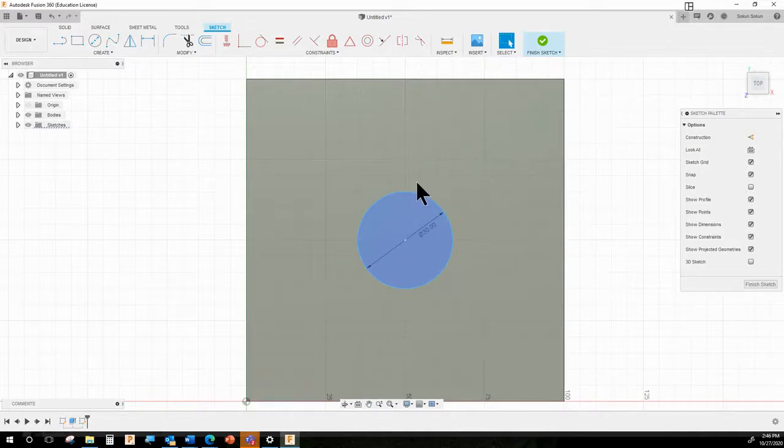Okay, so now if you did this right, if you got rid of any extra little weird stuff and you chose the top surface of the square to draw on and not one of the little yellow work plane squares, you should see two different parts. There should be a blue circle here and a blue square and a gray circle here. If not, undo and try it again. And this is where sometimes beginners need help right at the beginning. So just reach out to me for help. And I'll get you past the first stumbling blocks that happen very early on in Fusion.